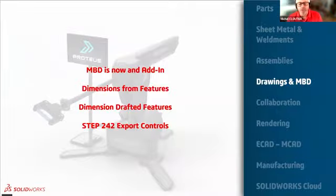So now with SOLIDWORKS 2025, MBD is actually a proper add-in, makes it much more flexible, especially in network environments. We can now dimension from feature dimensions, and create my 3D annotation from feature dimensions. We have better support for drafted features and also more controls for STEP 242 exports.